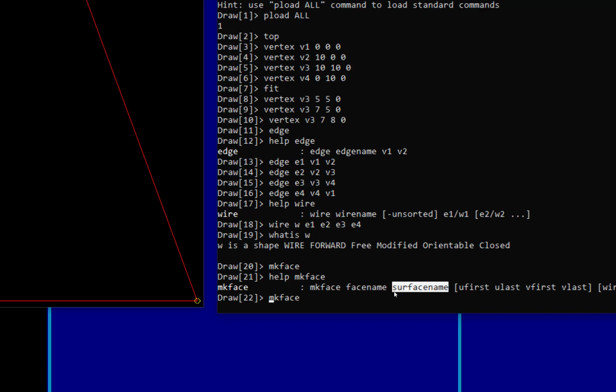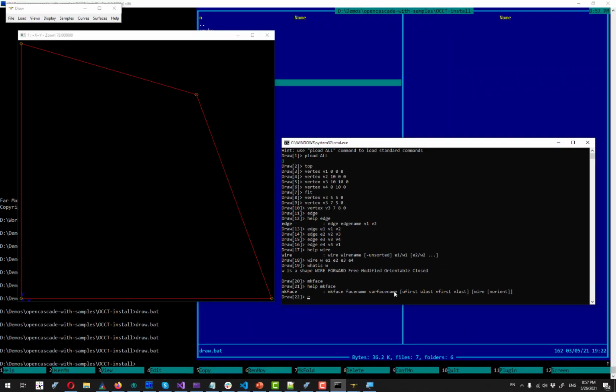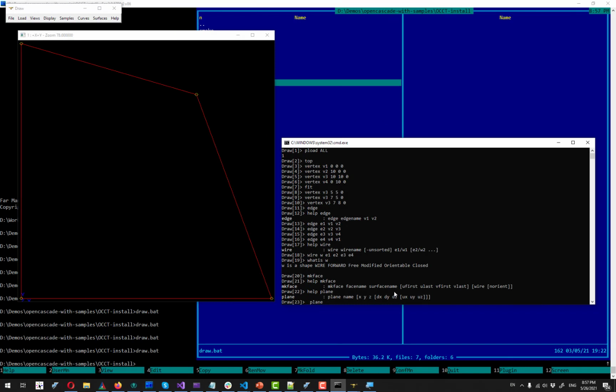So that is the right time to create a planar surface for our projection view. So I'm going to create a plane, and for a plane let me give it a name again, and now I need to specify its origin point. So let's put the origin, like the origin of our local coordinate system which is associated with our plane, right into the origin of our scene here.